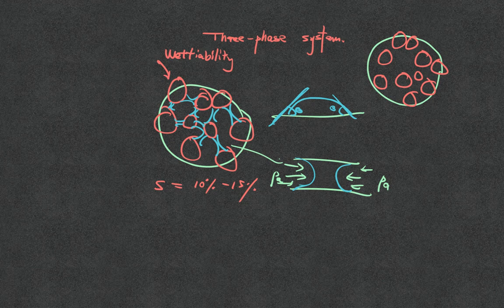It can take energy to deform it, to shear it, if it's under compaction. But in tension, it doesn't make sense for the sand assembly to be in tension. Individual grains can be in tension if you grab it and extend it, but not the entire assembly. The assembly doesn't really have any tensile strength.